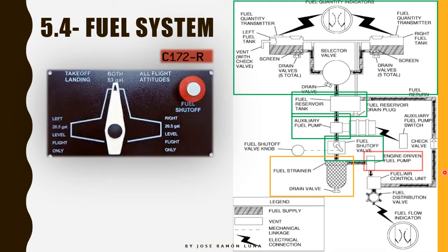After that, we have the engine-driven fuel pump. Okay, so this pump is driven by the engine all the time. The engine's moving, and it's pumping, sucking all this fuel from the system inside of the engine, okay? Because it's an injection engine that needs a positive pressure, okay? We need a positive pressure, and that's why this engine-driven fuel pump is going to be working all the time at the same time the engine's working as well, all right?